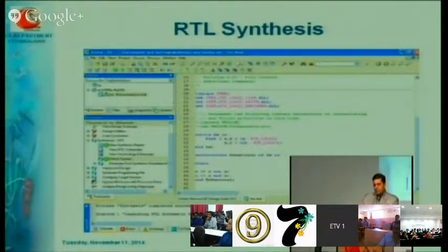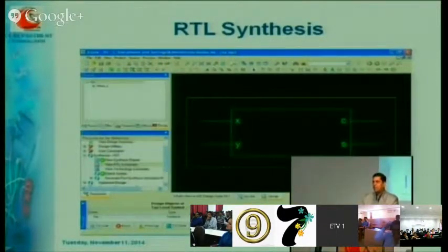Now this RTL description will be taken by the next section, that is the RTL synthesis section, and it will convert it into its equivalent, you can say, register level. Means one block will be created, and here you can see that X and Y, two inputs, are there, and this is basically the block for the half adder, and we have two outputs, sum and carry. So that VHDL code has been converted into this block with its inputs and outputs. You don't know about the internal architecture of this block.